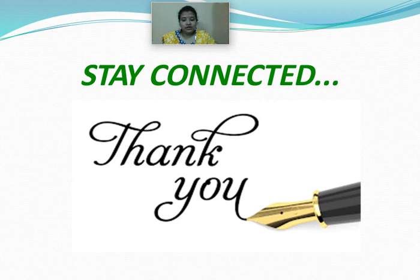The breaking point or the ultimate fracture point is very essential for all of us to know before we study the theories of failure, because these theories depend upon the load, that is, to what extent the material is able to absorb that load. And then finally we have discussed the maximum principal stress theory, and from this theory we have come to the conclusion that this theory holds good for your brittle material.